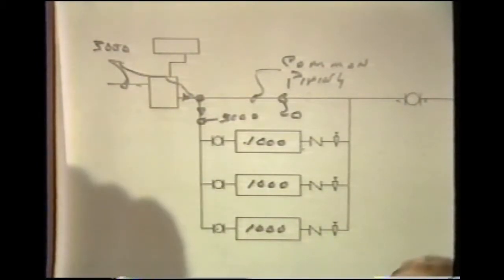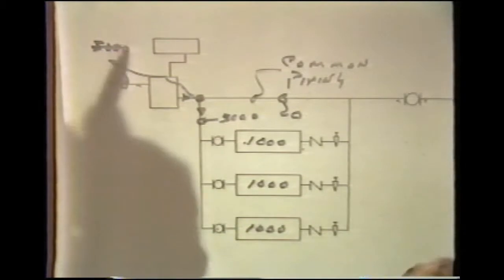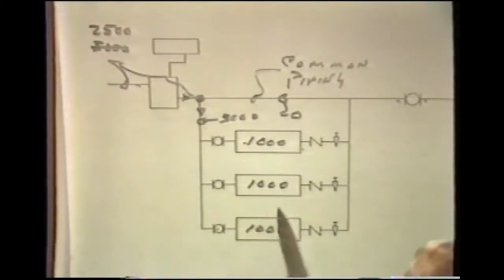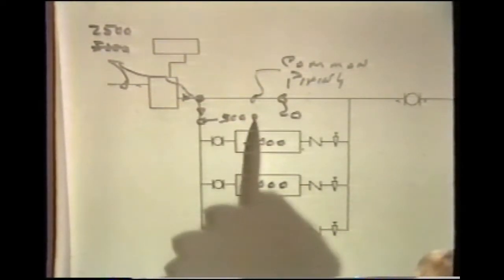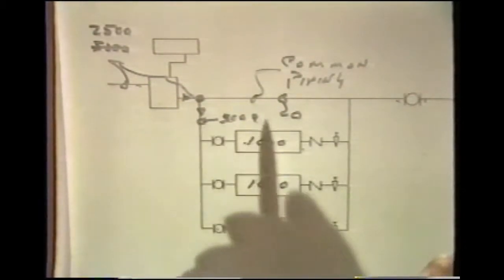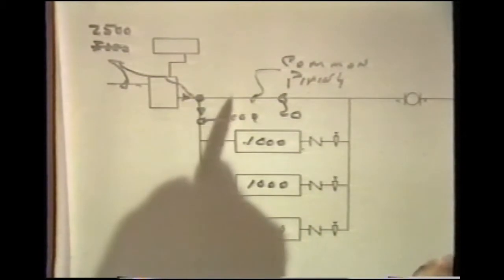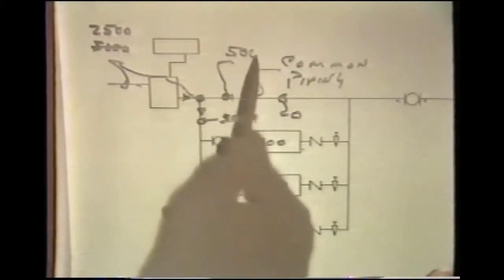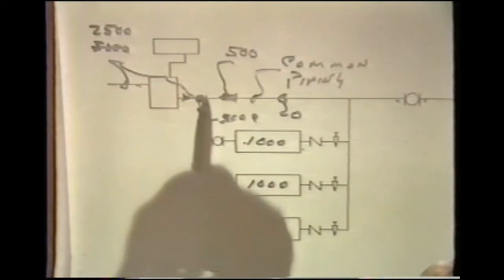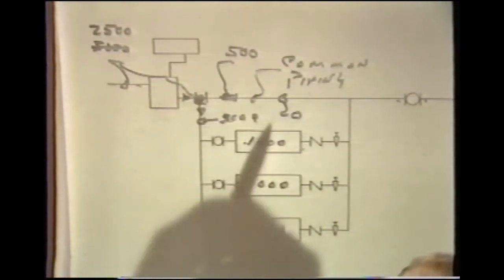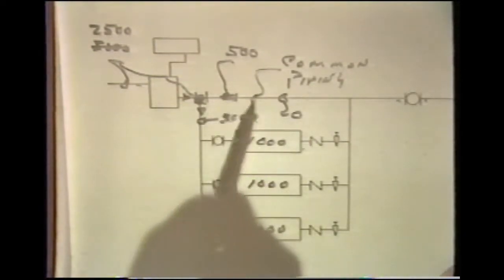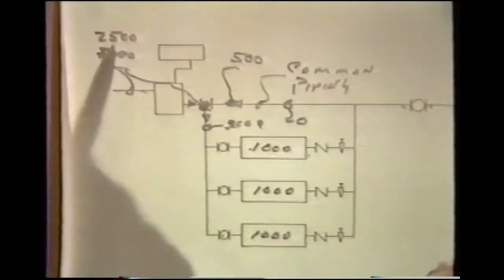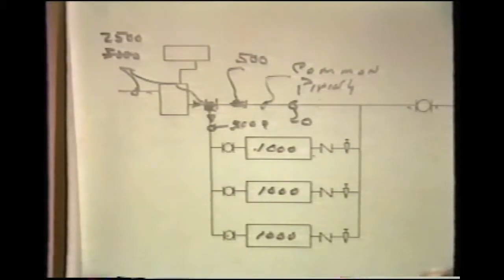Now, given that the two-way valves change flow in the distribution system, and let's say reduce the flow rate down to 2,500 GPM, with all chillers in operation, we're still pumping 3,000 gallons a minute away from the T. Because we're only introducing 2,500 GPM, we will then establish a flow rate in the common piping directed to the T at the return side of the chiller loop in such a way that we are mixing 500 gallons per minute of leaving chilled water with 2,500 gallons per minute of return water from the system.